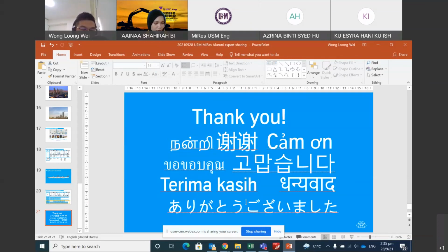But at the same time, with the current technology, there are a lot of green initiatives or green proposals on how to reduce the carbon emissions or carbon footprint in the cement industry. So I can give you 4 examples. The first solution, what can future cement plants do to reduce the carbon footprint? One of the things that is very practical and already installed worldwide is to use more alternative fuel besides the conventional fuel. For example, like I mentioned, instead of using coal and petcoke, which release a lot of CO2, you can switch to alternative fuel like tire chip, wood chip, RDF. All this can greatly reduce the carbon release.